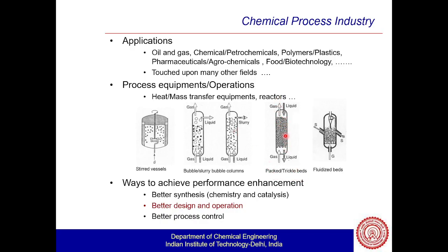So typically the gas can be co-current and counter-current, and the liquid actually spreads on the solid bed and the gas comes in a co-current or the counter-current direction, but the gas and the liquid basically react with each other. And these fluidized bed reactors, where the reactor is filled with solid particles, and then gas gets injected from the bottom of the bed, and these bubbles get formed where the gas comes in contact with the solid itself, and then they react and the product is being formed and it goes out of the reactor.